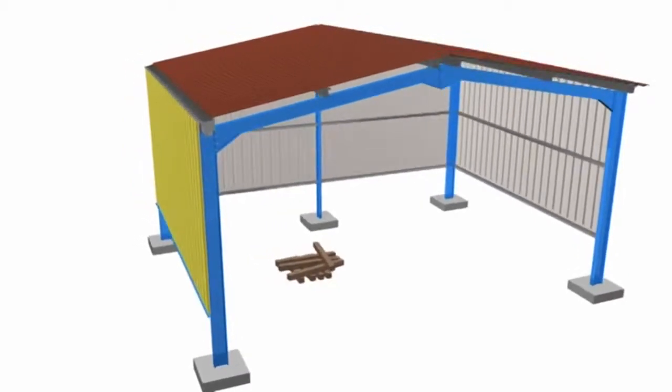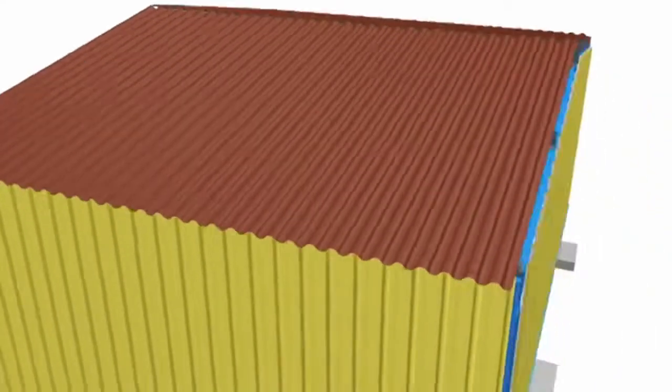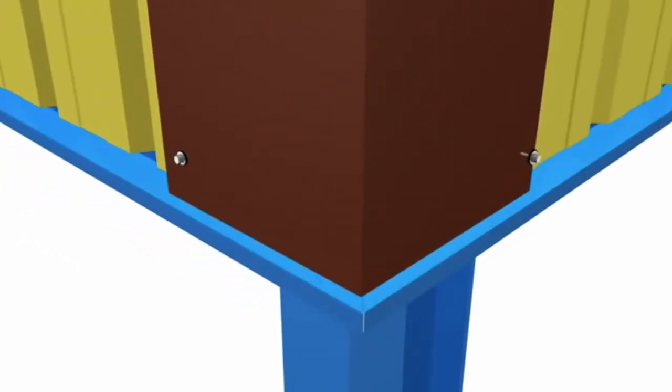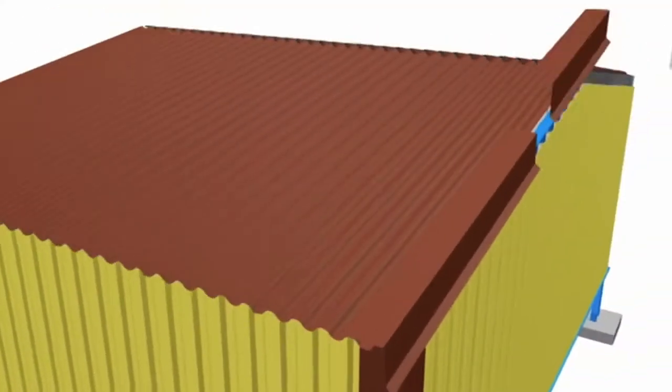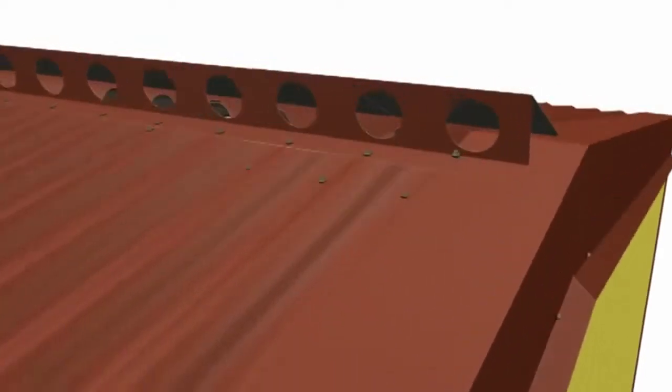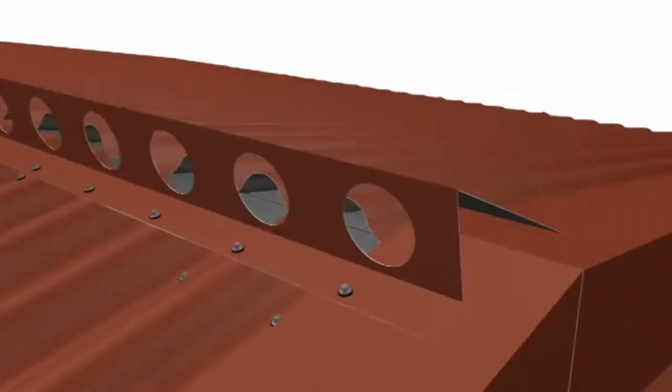Case 2 was now calculated to determine the maximum moment force and corresponding normal force. The final calculation which was to be completed was determining the column capacity for the combination of compression and the bending moment. However, the total was greater than 1, meaning a recalculation had to be done.